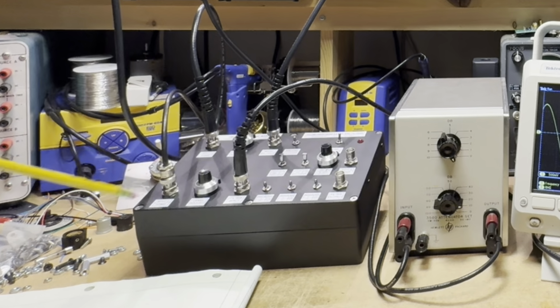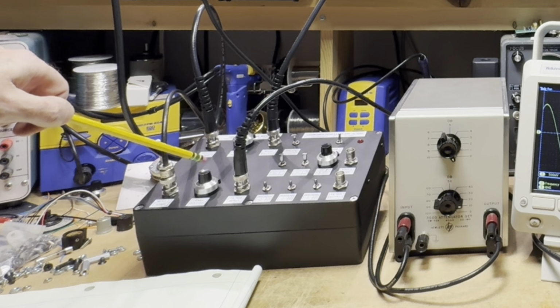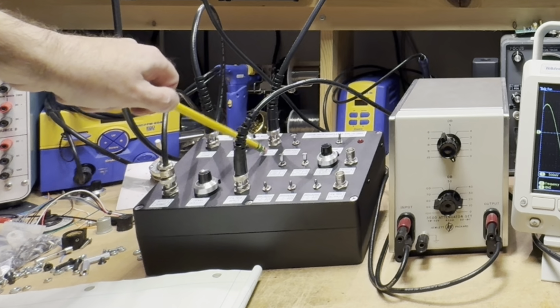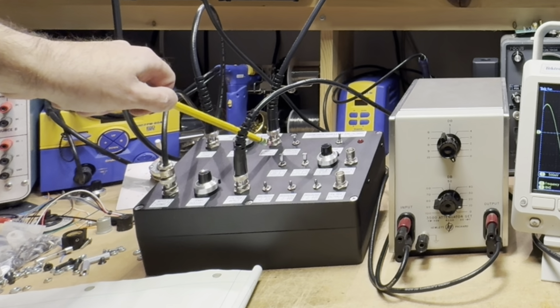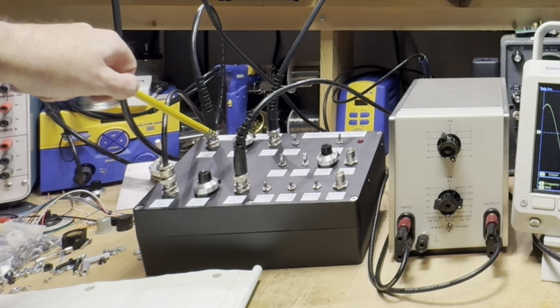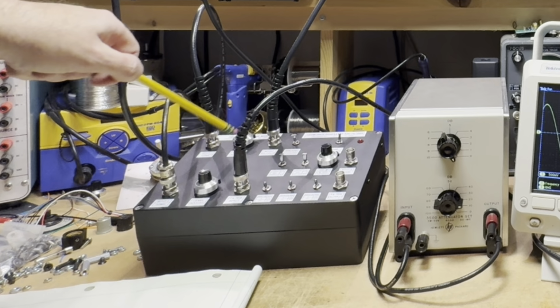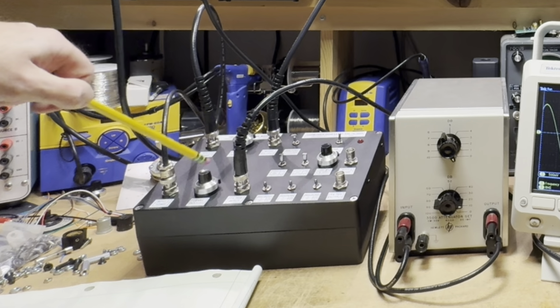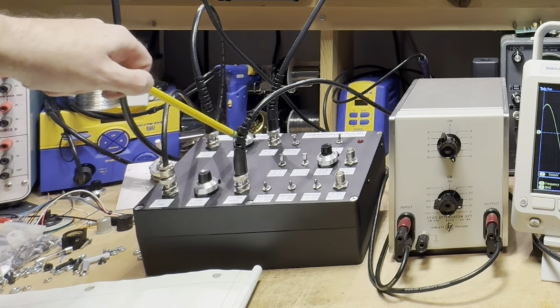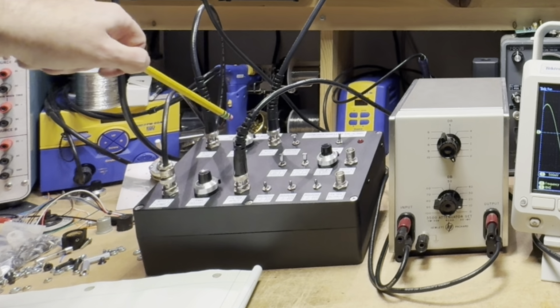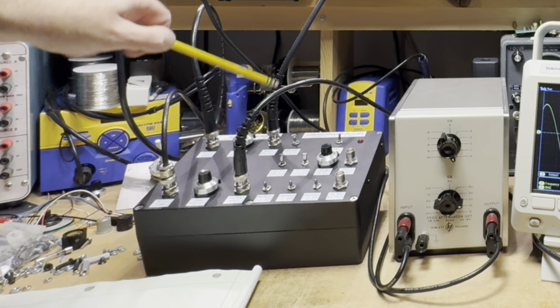The output of the attenuator goes into channel 2 of this mixer box, with the potentiometer also set for a maximum signal level, and these two signals are mixed here at the output of this box. So this output here is a mixed combination of channel 1 and channel 2. I haven't taken this apart, but there's a buffer amplifier in each of these, and then they're mixed with a summing amplifier so that the two will minimize interactions with each other.